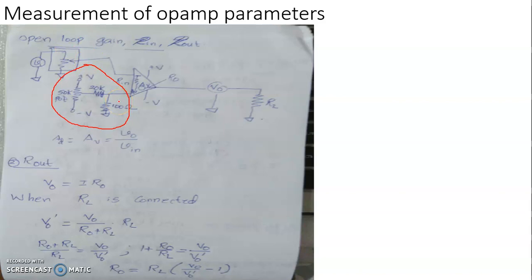So before going to measure this parameter, we will have to ascertain this thing, that is universal balancing is being applied and input offset voltage is compensated. The second thing that we have to take care of while demonstrating the measurement of open loop gain of an op-amp is that we ascertain that the input signal is a zero noise signal or a minimum noise signal that have the capability to be reduced to an extremely low value of the order of a few microvolt.